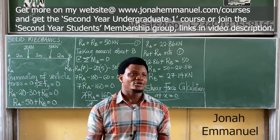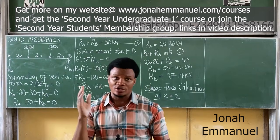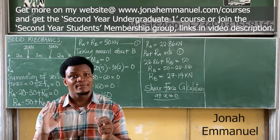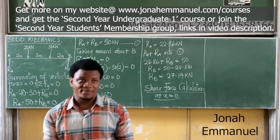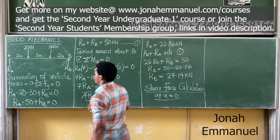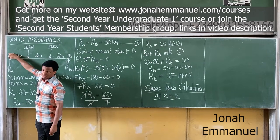To do shear force calculation, you ask whether the force there is going up or coming down. If it's going up, take it as positive. If it's coming down, take it as negative. At x equal to 0, do you have a load there?